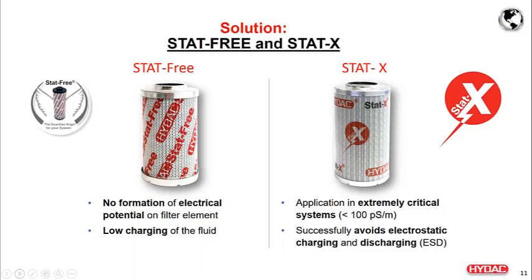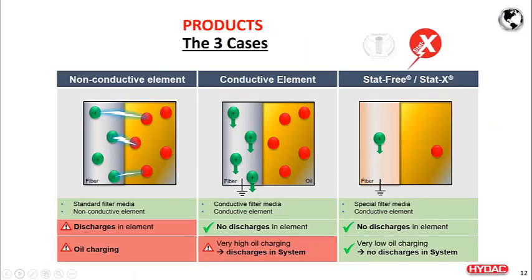StatX filter, on the other hand, is a very sophisticated design, modified glass fiber media, that helps you reduce the charge generation, or almost no charge generation, at a lower conductivity, as low as 2 to 3 picosiemens per meter, and provides you no charging of the oil in the hydraulic or lube application system.